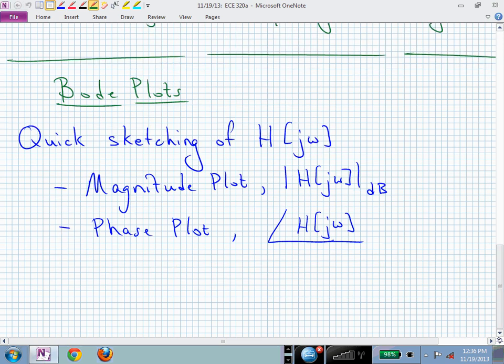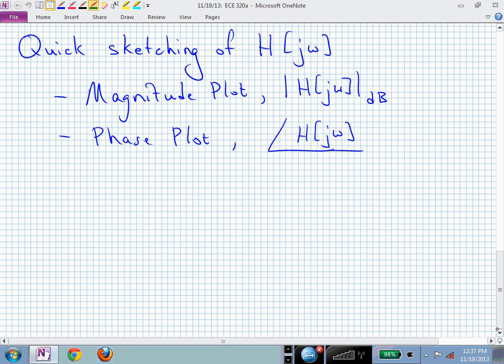What we are going to be looking at: you can sketch Bode plots for poles and zeros everywhere in the complex plane, but we are going to emphasize those that have all of their poles and zeros in the left half plane. We can have poles and zeros on the imaginary axis, but we won't deal with non-minimum phase zeros or unstable systems when we're sketching Bode plots. It simplifies these techniques. So I'm going to say that the techniques we are going to be using or describing are for minimum phase.